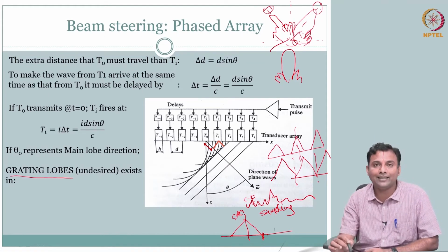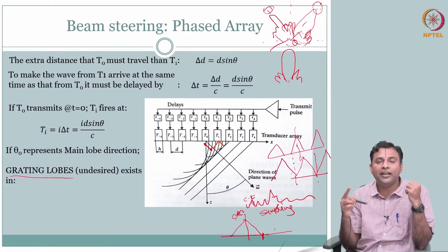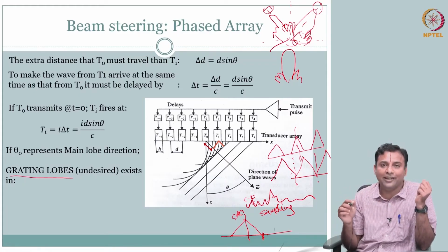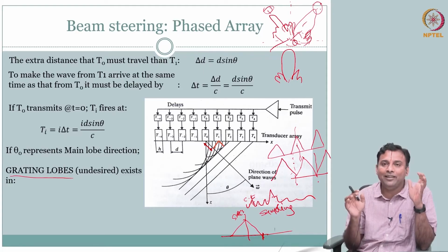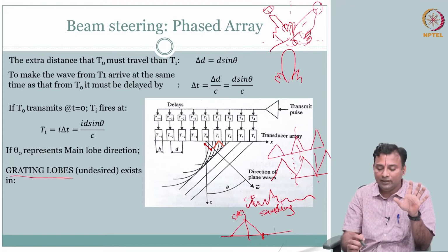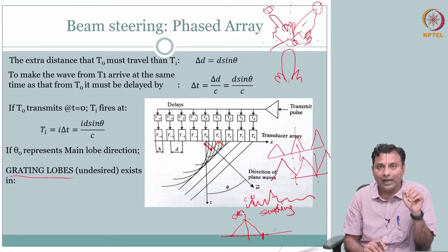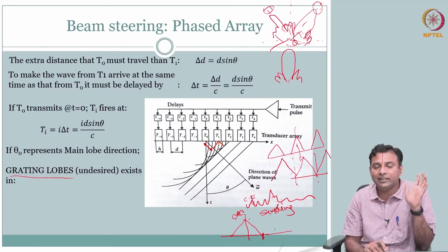When you undersample, when you go below the Nyquist, you will have overlap, and so we call it high frequency masquerading as low frequency, all these textbook definitions. Practically what is happening? Practically you have replicas of the fundamental spectrum. When you sample it, you have to sample such that it is not going to overlap. Okay. So this is what you know from your basic time-based 1D digital signal processing.